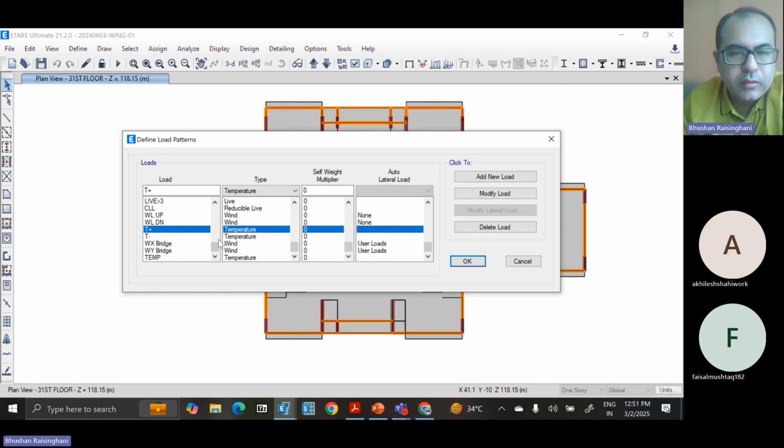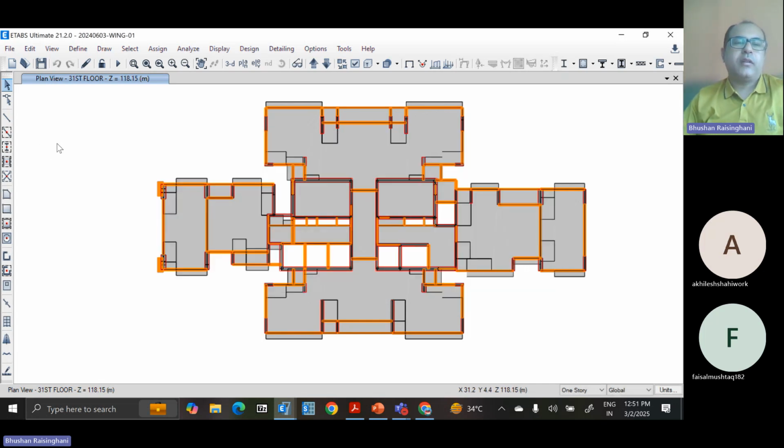Some error in which there was some application from the given requirement. So temperature load is also applied here, in this particular case. Construction load, all those, whatever the loads are coming, overhead water tank, then on the stilt floor, there is a fire tank. So all those loads are applied at each floor wherever it is required.